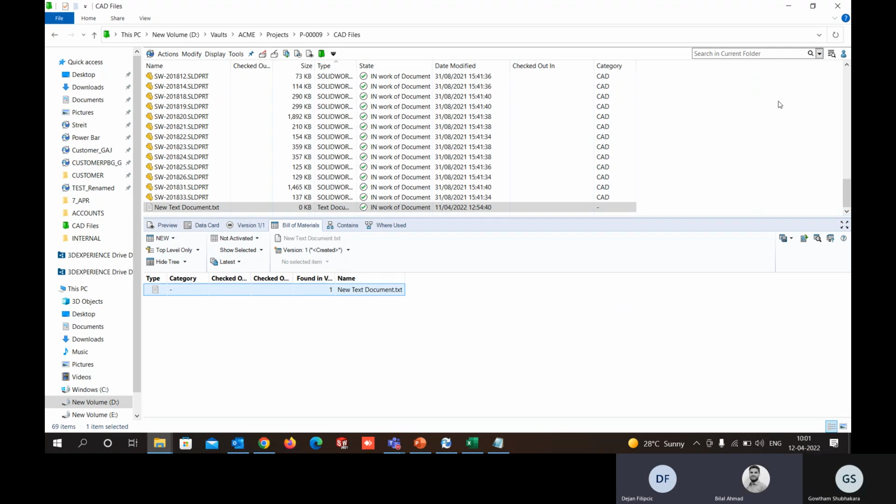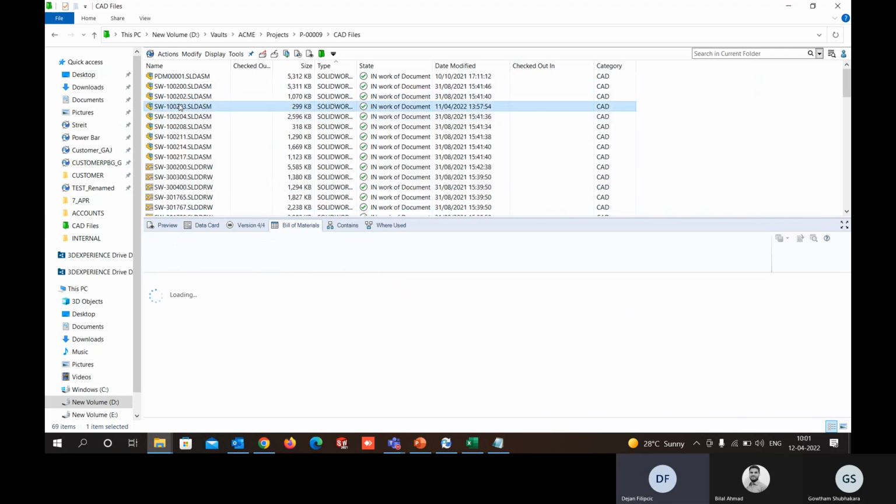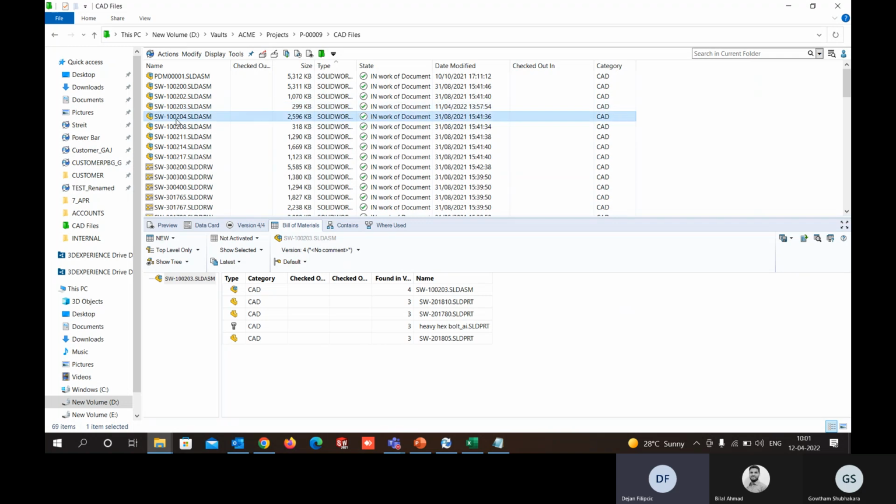Okay. If you look at flat parts, we're talking about sheet metal parts that are cut, bent or both. For those parts, what you obviously need is a cutting file, which is a DXF. We could also load a 3D file and the software will unfold it, that's also possible.